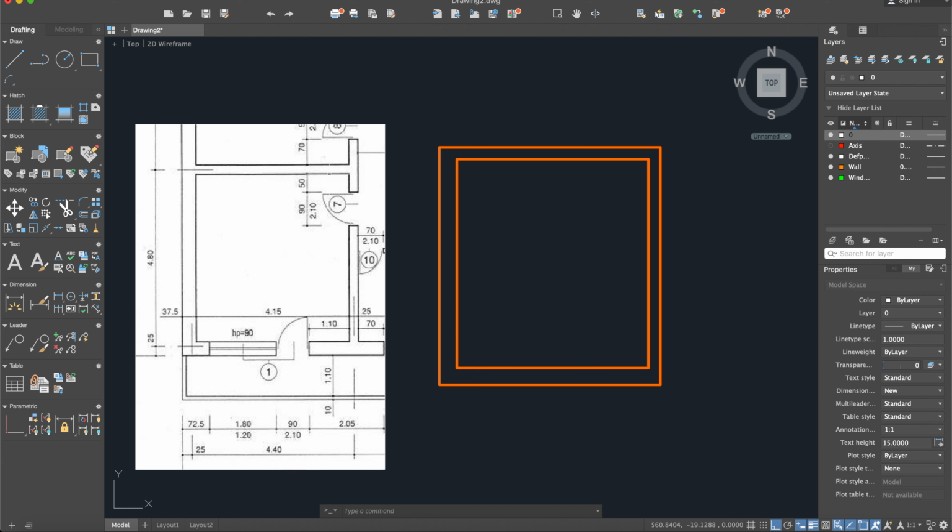Next up, we have a door, first of all. So this is exactly what we will do. But I will change the layer first. I will put this one on windows and doors. I will draw a line because here we have a length of 50 and our door is 90. So here, okay, and now I will apply the offset command for 50. And for our door, again offset, but 90 units this time.